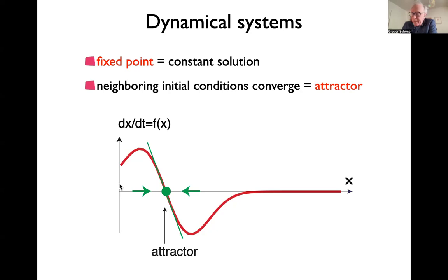And we're using this for these behavioral variables, and therefore we're using this as a method of planning. And so when you have a system like that with an attractor, if now the red line deforms, moves around as sensor information changes, it's this very attractor property that makes the state space track the attractor. So if it shifts, the state will also shift and follow the attractor, right?